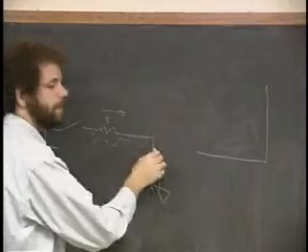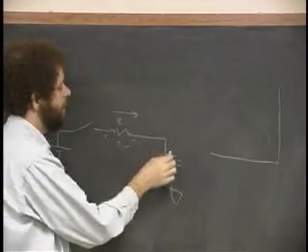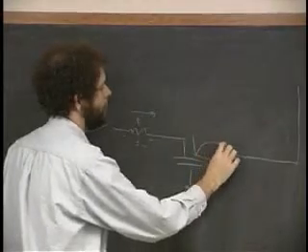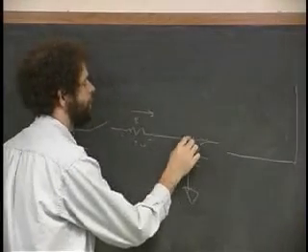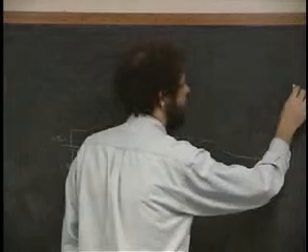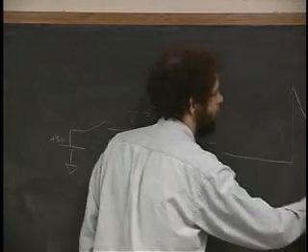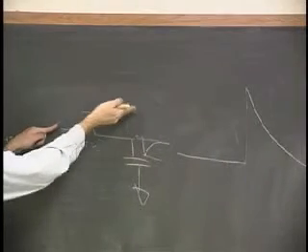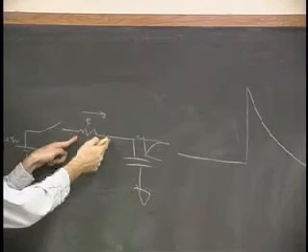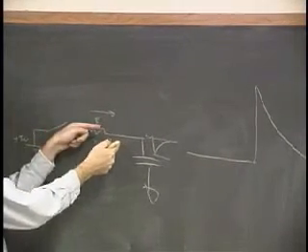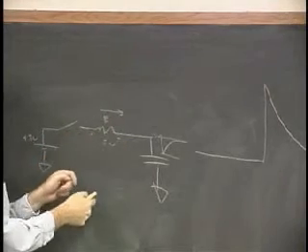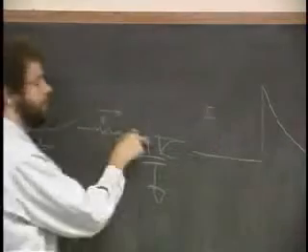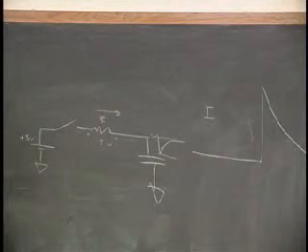But very quickly, this thing begins to fill up, right? And as this thing fills up, and the voltage, as it fills up, kind of looks like this, where this is 5 volts here, the amount of current that goes in starts to go down and looks like that. And the reason is that as this thing fills up, the voltage across the resistor goes down, and the amount of current that you end up getting to fill it up goes down. Okay, so this is the I, the current going into the capacitor over here.